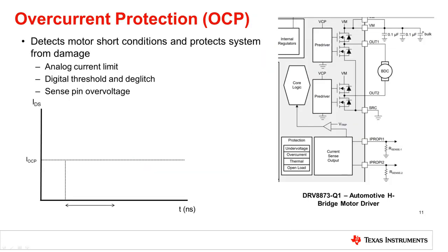The third and potentially most important feature on motor drivers is overcurrent protection. When driving a motor, power MOSFETs are used to control the PWM switching from the gate drivers. If there is a short to VM, ground, or a shoot-through condition occurs, then overcurrent conditions must be monitored to prevent the FETs, motor, or motor driver from failing or being damaged.